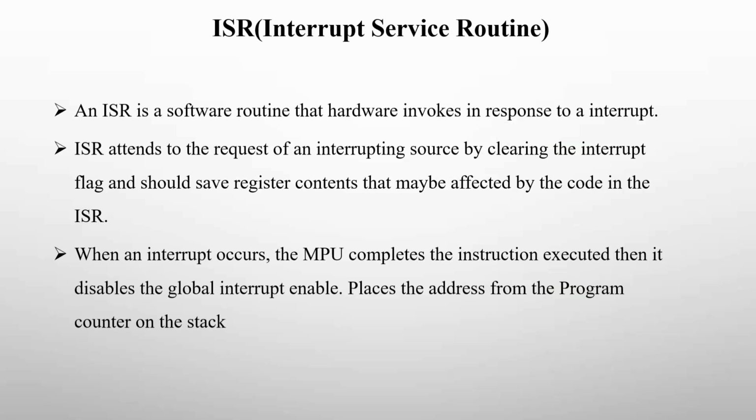ISR is triggered when an event occurred, ensuring the system responds instantly. Say the microcontroller is busy executing the infinite loop. During that time, external devices or internal devices will request the processor to stop the processing. Then processor will stop the processing and attend the request and come back to the process where it was interrupted.